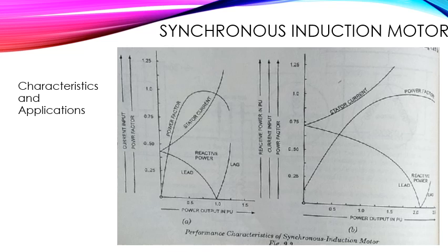So in such motors, the DC field winding is of normal construction and an independent three-phase starting winding connected to the slip rings is placed in slots in the pole shoes. So each winding can be designed almost independently to fulfill its own function, with consequent improvement in synchronous running and exciter circuit conditions.